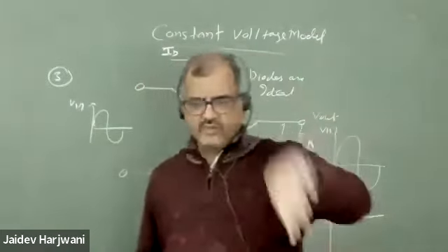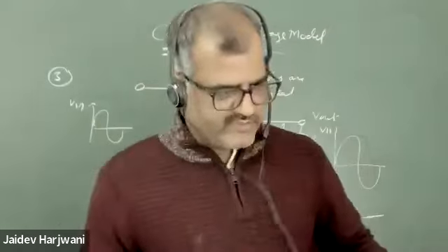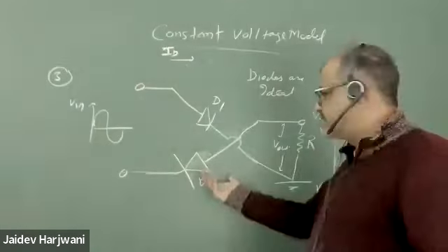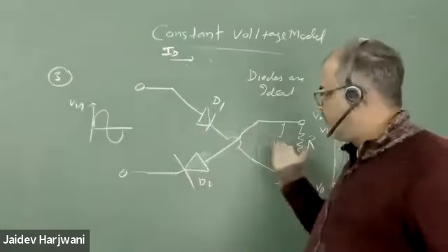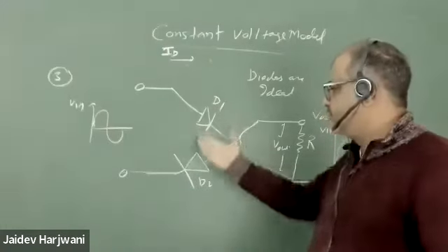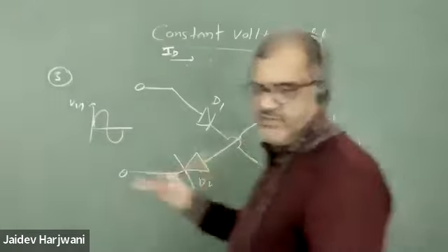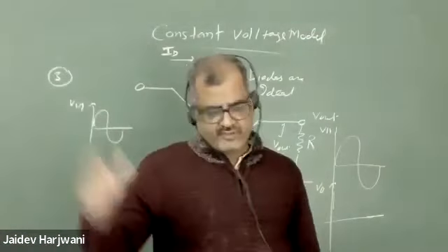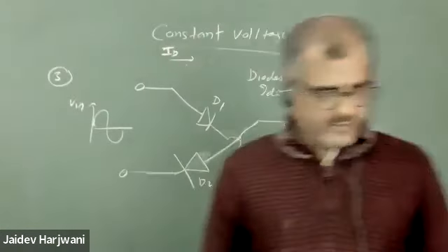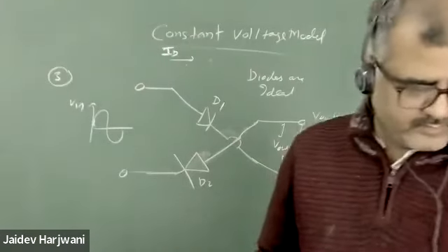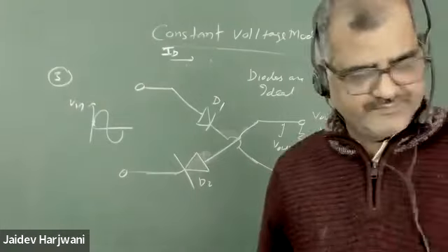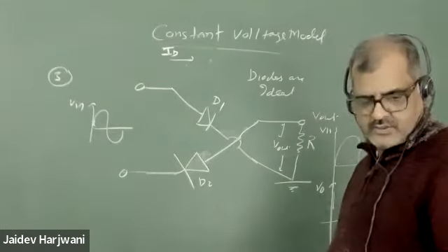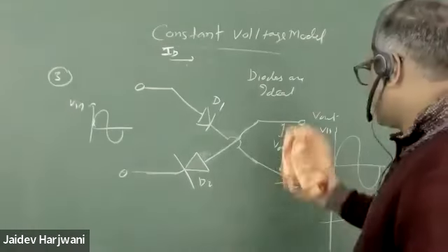You just need to show the variation, how it is varying. Because these are models, the whole voltage will drop only across the resistance. There will be no other voltage drop. So the magnitude will be the same for V input and V output. Just show me the variation. Are you getting my problem? There is no other voltage drop in the circuit, so whatever voltage drop there is will be across R only.